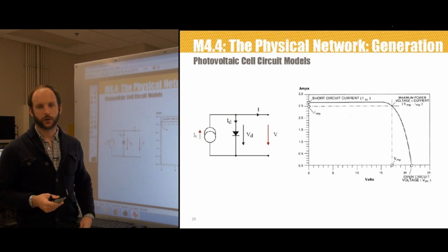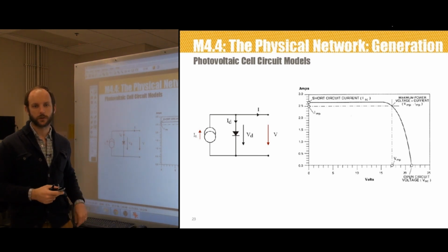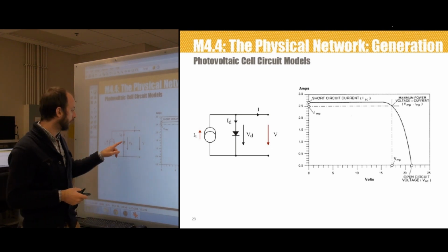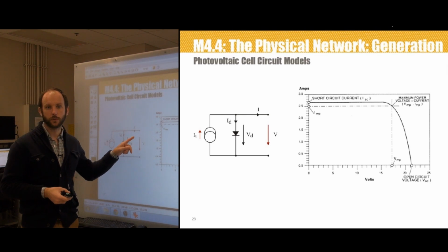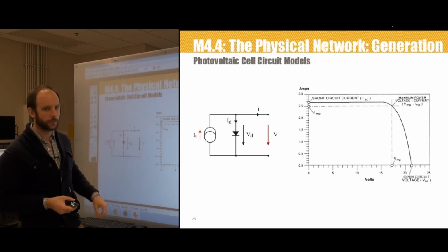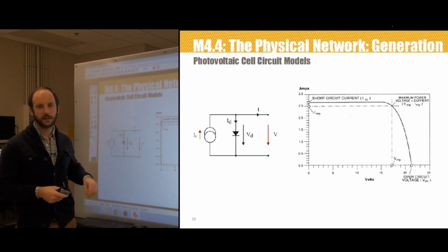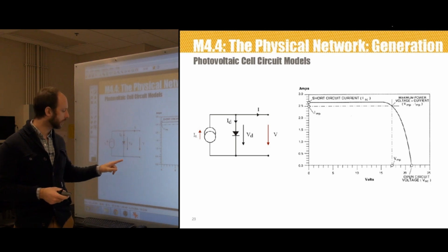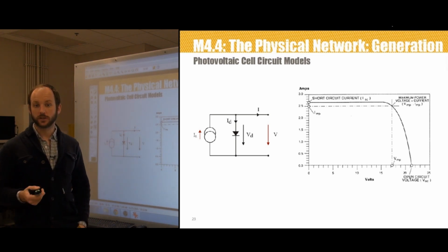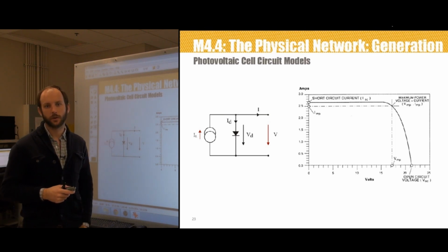And the voltage across the terminals when the leads are left open is called the VOC, the open circuit voltage. When the leads of the PV cell are shorted, no current will flow in the diode because that voltage will be 0 volts, so no voltage drop across the diode. All of the current from the ideal source, ISC, therefore flows through the shorted leads. This short circuit test gives us the value of ISC in our circuit model,